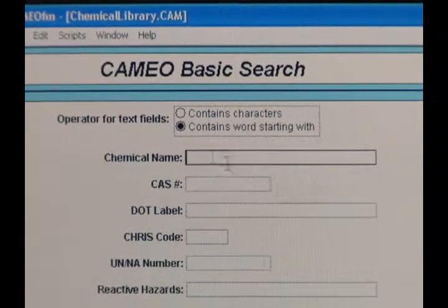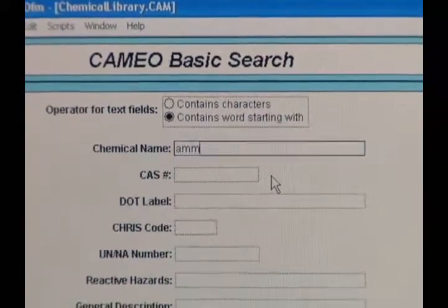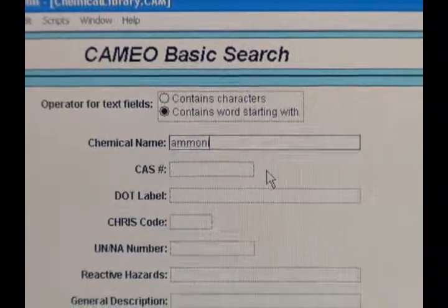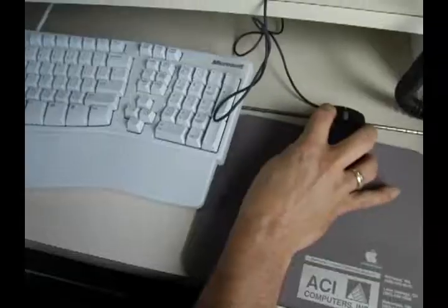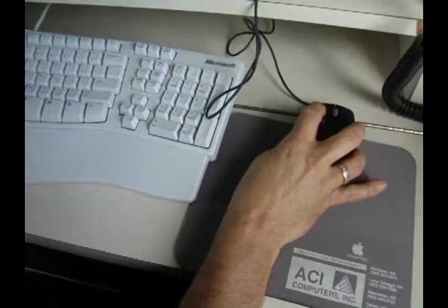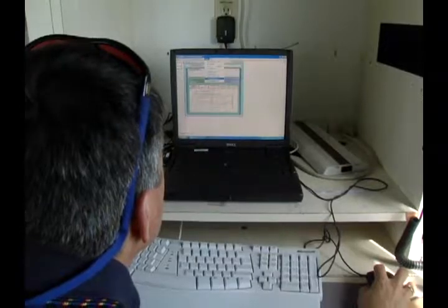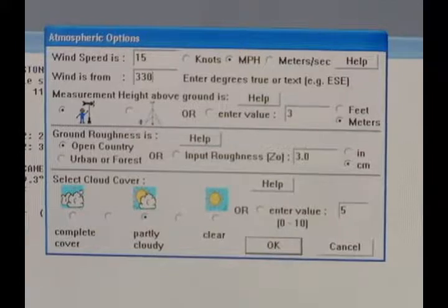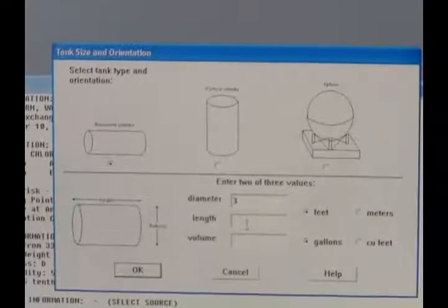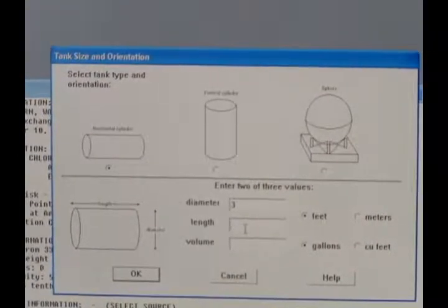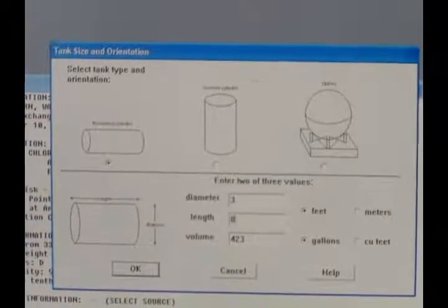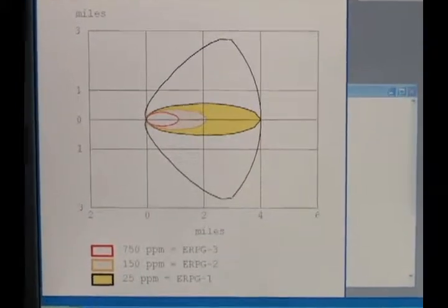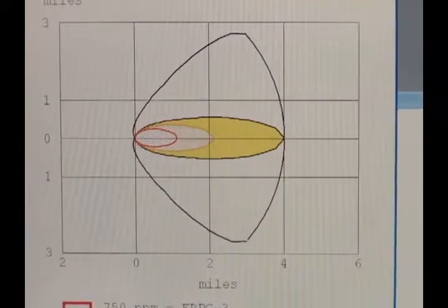CAMEO is plume dispersion modeling software that can help determine the impact of hazardous vapors in specific areas surrounding the incident scene. CAMEO includes a chemical library, facility library, and an electronic mapping program. CAMEO also factors in wind direction, wind speed, and other physical and environmental factors to create a simulated footprint of the vapor cloud superimposed over a map of the area. Your team will be able to determine what areas will be impacted and the size and scope of the problem.